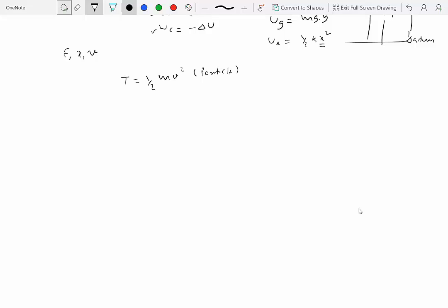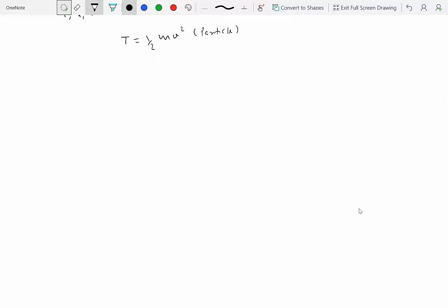On the other hand, the expression for the kinetic energy for rigid bodies is slightly different from this. So let's first try to derive that. You will recall that the kinetic energy for a system of particles was given as sigma 1/2 m_i v_i squared, where m_i is the mass of particle i and v_i is the speed of particle i, right?